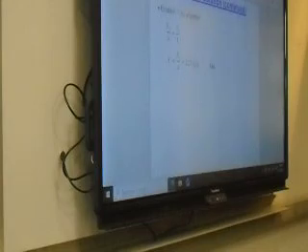What shall I do? This is a very clear example of what we call a K-truss. Very classical case of something like that. If I take a cut here, or here, or here, anyway, you're cutting through four members, and you're having only three equations.